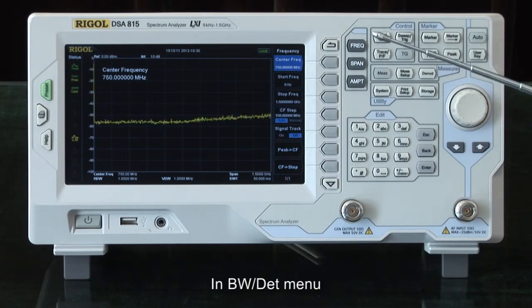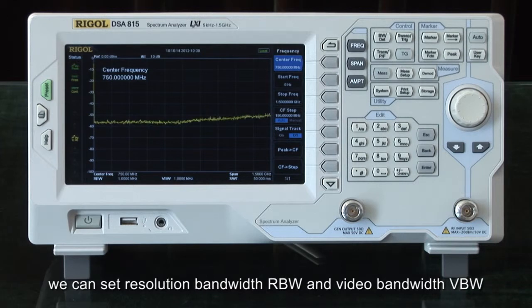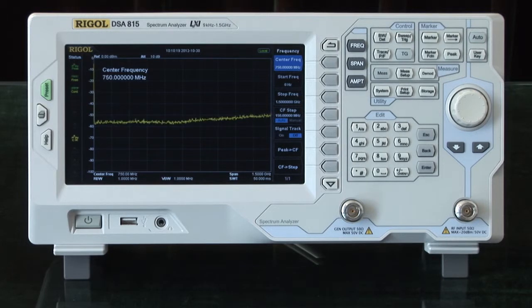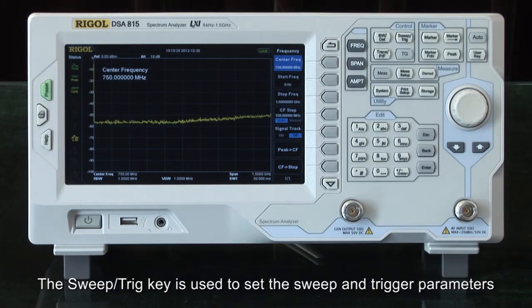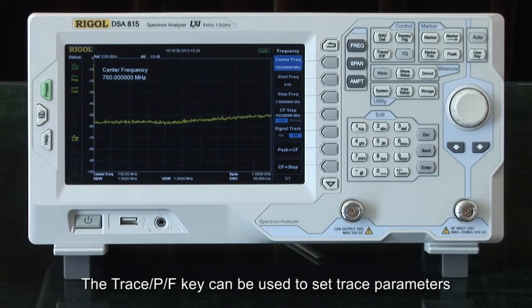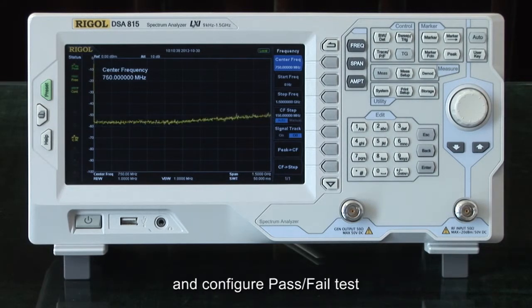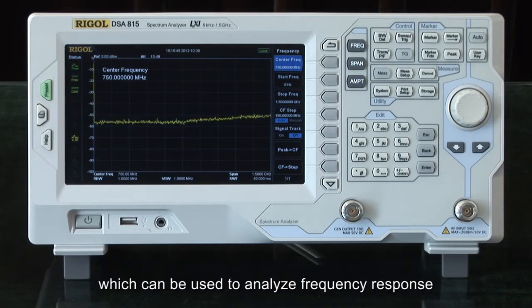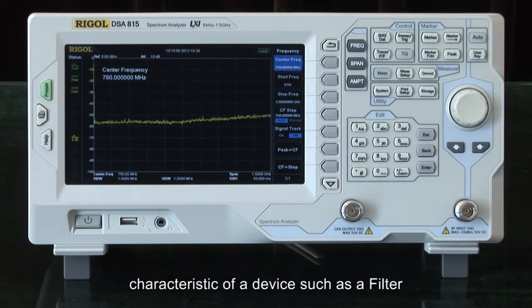In the bandwidth detector menu, we can set resolution bandwidth and video bandwidth, as well as select the detector type and the filter type. The sweep trig key is used to set the sweep and trigger parameters. The trace pass-fail key can be used to set trace parameters and configure the pass-fail testing. The TG function can output the sweep signal, which can be used to analyze frequency response characteristics of devices such as filters and amplifiers.